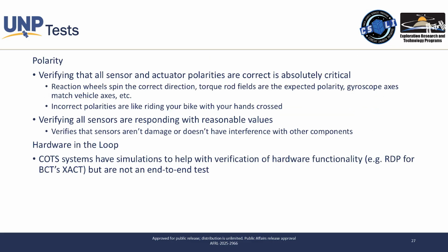So for testing, we highly recommend doing polarity testing, and that's literally like if I hook up my reaction wheel, when I say I want it to spin up positive, is that in fact positive and negative is negative? You could easily screw yourself up if you literally just plug things in the wrong way. Do I physically, electrically have things connected properly? And this is true for your sensors as well. If you think the vector's this way, but it's really that way, that could really mess you up.